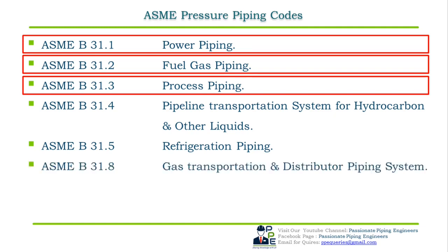The next one we have is ASME B31.8, that is for gas transportation and distribution piping systems. This code is typically used for gas transportation piping between sources and terminals, just as in the case of offshore and onshore pipeline facilities used for transporting gases. Piping at compressor, regulating, and metering stations, gas distribution systems, and gathering pipelines in respect to all pressure and temperature above 450 degrees Fahrenheit, that is approximately 232 degrees Celsius, or below minus 20 degrees Fahrenheit, that is approximately minus 30 degrees Celsius.